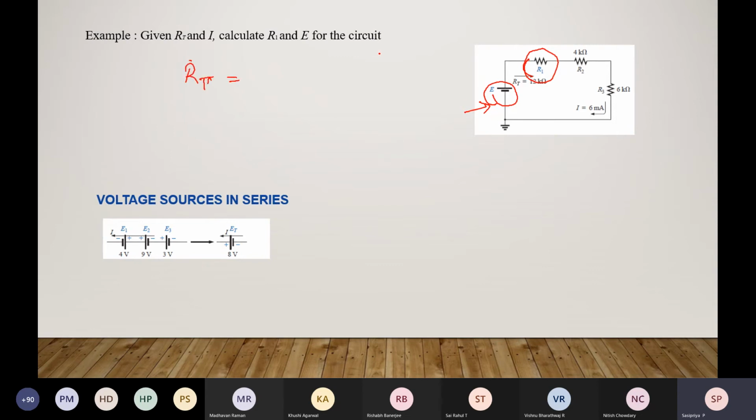So we know that this is a series circuit. So total resistance will be R1 plus R2, which is 4K, and R3 is 6K. Okay, so now from this I can find out what R1 is. Total resistance is 12K. So 12 minus 4 minus 6. So it's 2K.